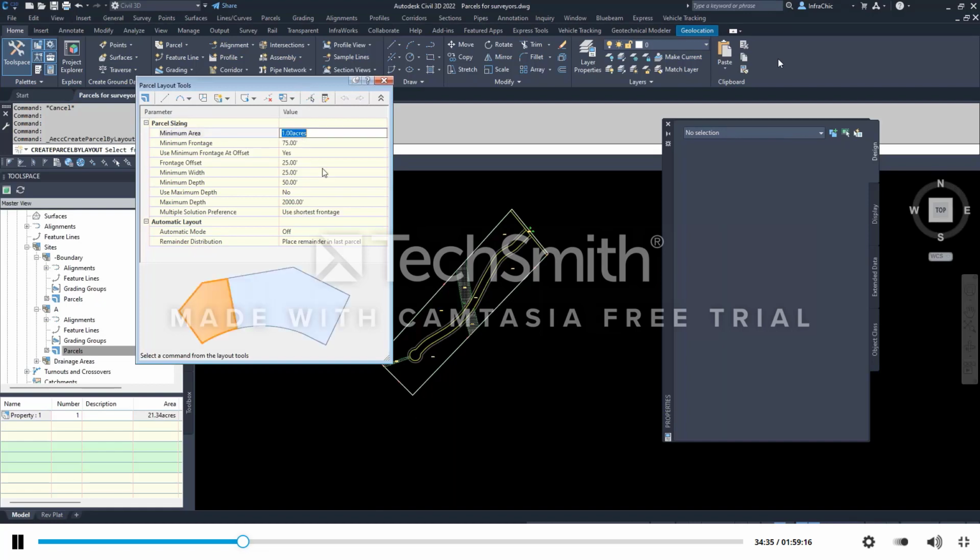Currently the parcel minimum, I needed a 1 acre minimum. My frontage is supposed to be 75 feet from lot to lot. My frontage offset, and that's 75 feet based on that 25-foot front offset. Okay. Minimum width, 25, minimum depth, 50. Do you want a maximum depth? In this case, no, because I don't know how shallow this is on this side over here.